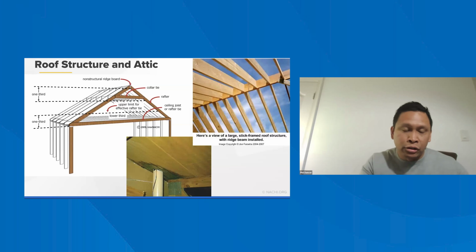Because again, remember, they're doing load calculations, not just on the dimensions of the rafters, but also based off of the species of the wood and how long the rafters are. So maybe based off of a certain design, let's just pretend that this is actually part of the blueprint for the house that you're inspecting. Maybe they already signed off on it and said yes, based off of how we designed this house, I don't need a double top plate here.